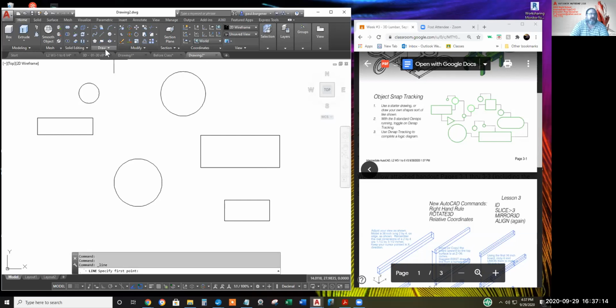I'll start the line command, click at quadrant, and it is automatically acquired, or the quadrant at which I started is automatically acquired. And you'll see your first point is usually automatically acquired. Be on the lookout. If you bounce over it, you can unacquire.